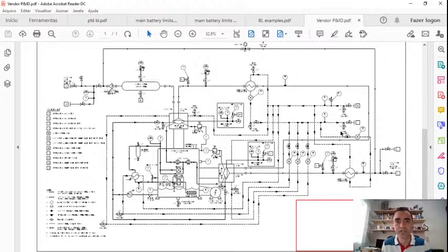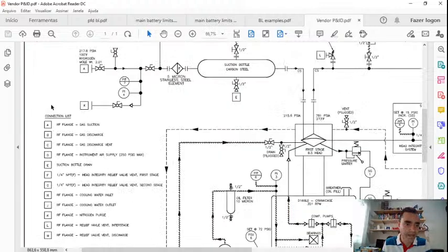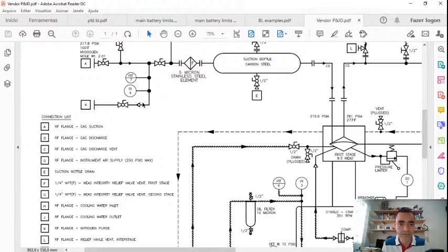When I need to do the maintenance of this equipment, I will close the inlet valve, the outlet valve, and all the content that is inside here must be safely released to somewhere. And I will use this valve here to release to my vent stack or to my flare system, so that after that I can add nitrogen to the system.